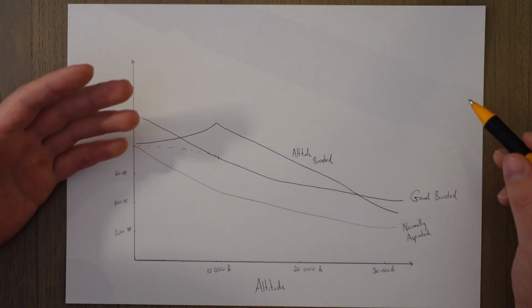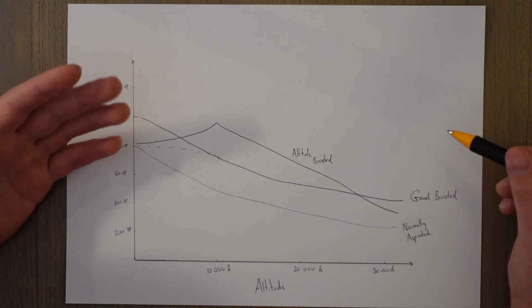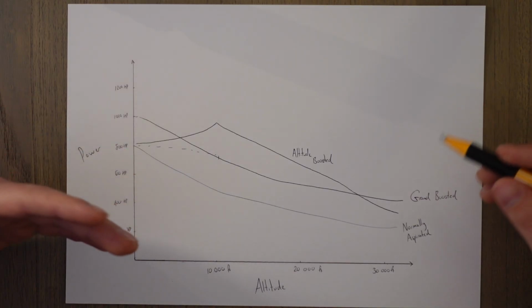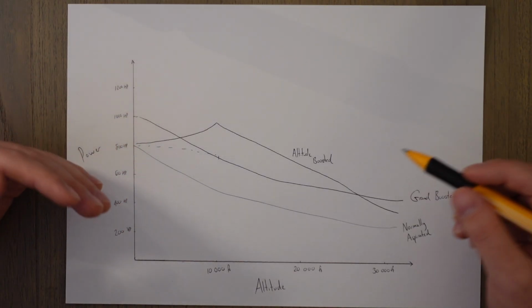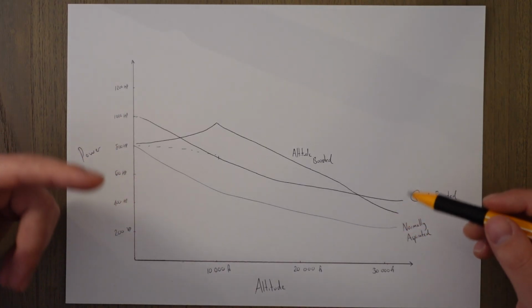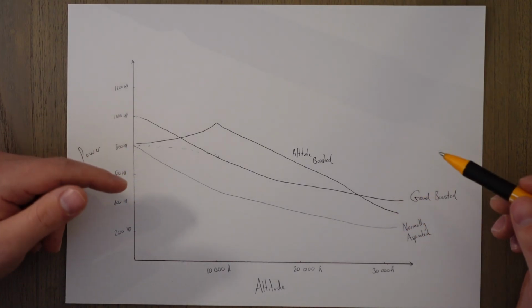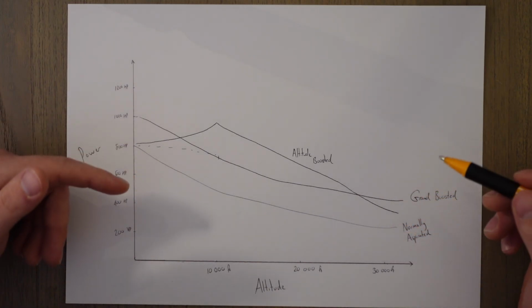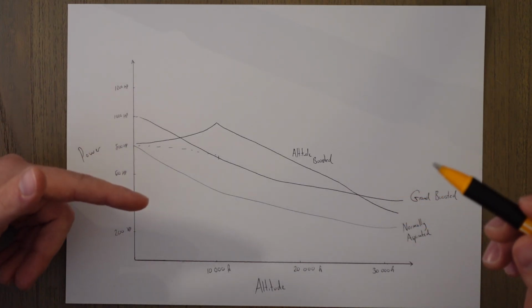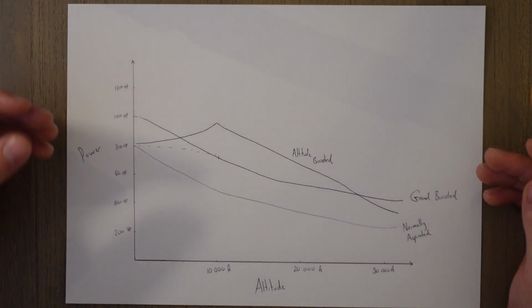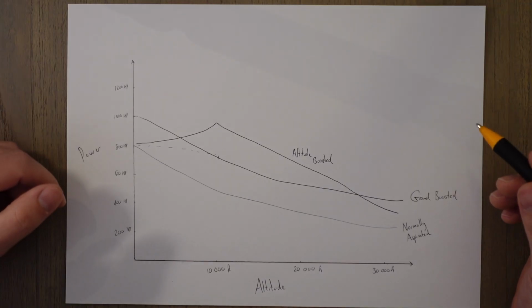The advantage of a turbocharger is that it doesn't use a big heavy system of gears and all that sort of stuff, so it's more lightweight. But because it's relying on the exhaust from the engine, there's a bit of what we call turbo lag. As the engine gets up to speed, the exhaust coming out the back needs to be fast enough to make the exhaust gases spin the impeller at the correct speed in order to draw in the correct amount of air and compress the correct amount of air.